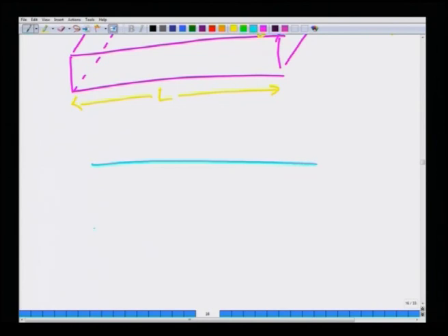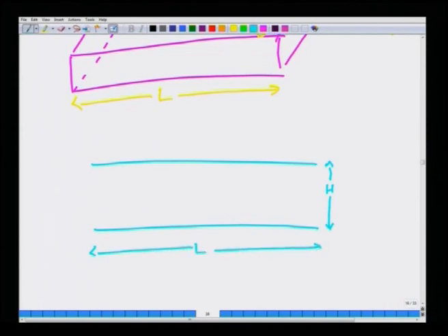So, you imagine that you have a channel, the height is h and the length is L, and you have a mixture of gas plus tiny solid particulates that flow in, and we want to make sure that when this mixture flows out, we separate out the solid from the gas, and that happens by virtue of the gravity which acts in this direction and settling.